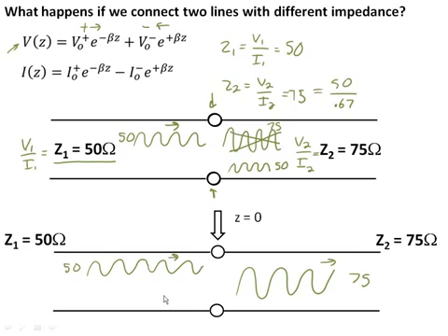Well, it would actually make sense if you had a second wave moving in the opposite direction. So we had a wave that summed up positively with the first wave, moving in the negative direction, that had an amplitude of 25. Because then, right at this point, where these two waves add together, you've got a total of 75, which equals the voltage on the other side.